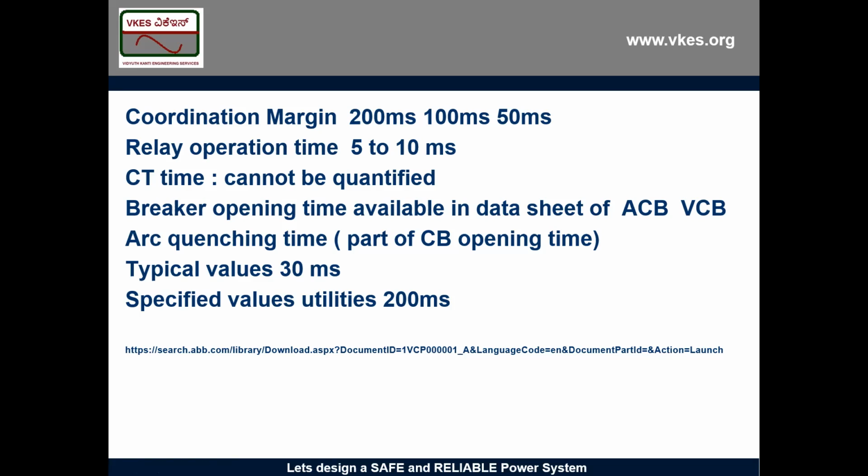So that will also depend on the number of levels also, no? Number of breakers in that whole sequence. Yes, the number of levels, number of breakers will depend. But first we are choosing the margin. First and foremost, the coordination margin, normally the owner is giving, we are taking. And as the number of levels increases, you have to reduce the coordination margin sometimes. But I will tell you, you fix the coordination margin in the beginning of the project itself.